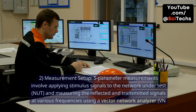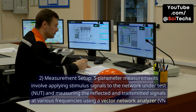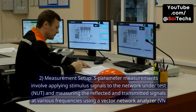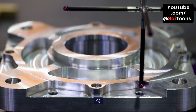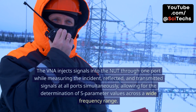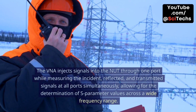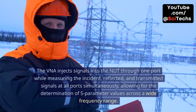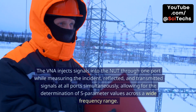2. Measurement setup. S-parameter measurements involve applying stimulus signals to the network under test, NUT, and measuring the reflected and transmitted signals at various frequencies using a vector network analyzer, VNA. The VNA injects signals into the NUT through one port while measuring the incident, reflected, and transmitted signals at all ports simultaneously, allowing for the determination of S-parameter values across a wide frequency range.